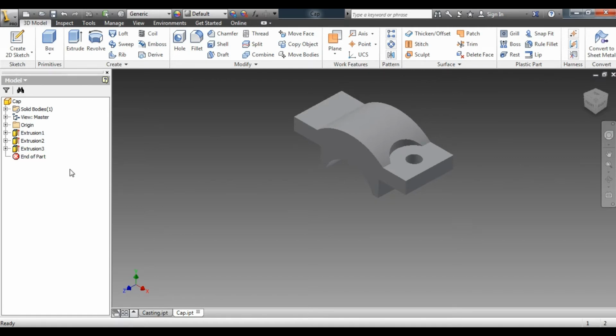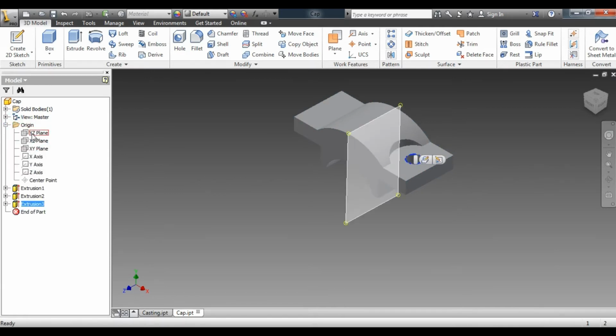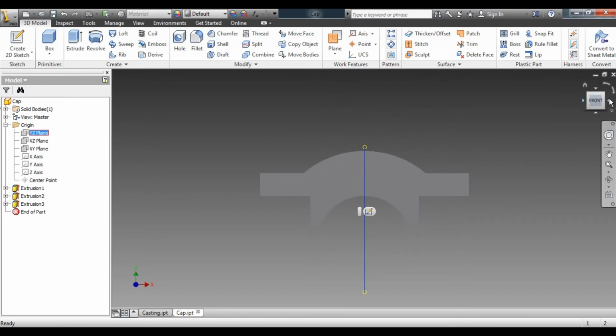For that, which command you have to use, we have to see first. So this is the main part which is not required to replicate. This is the part you have to replicate. Second and third should be replicated. For that, they are asking for the mirror plane. So you have to select the mirror plane. This is the right mirror plane, which is from the middle, right?